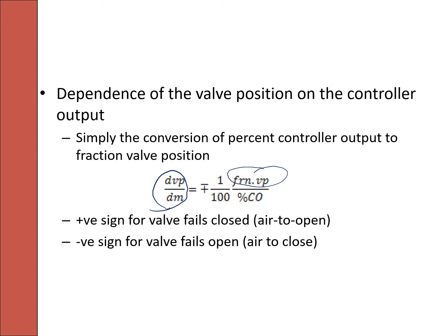The positive sign is for valve fail close, which is air to open. The negative sign is for valve fail open, which is air to close.